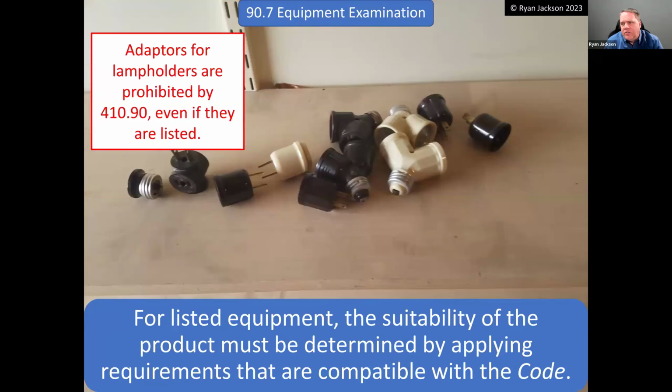The last thing that it says here in 90.7 I think is kind of important. It says listed equipment, the suitability of the product needs to be determined by applying requirements that are compatible with the code. Okay, so in order to have a product listed, there has to be a product standard, right? And the product standard is going to say how the product is supposed to perform. It must have an ampacity of this many amps, and it must not exceed this temperature and what have you. And then we send our products over to UL or Intertek or whomever, and they test it and make sure it complies with the product standard.